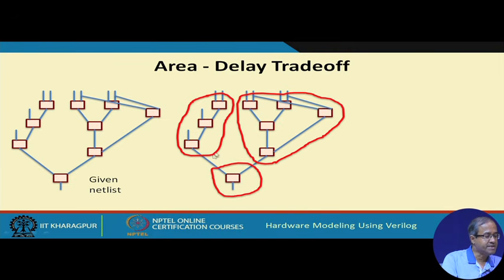If I take this whole part, there are total 4 inputs, 1, 2, 3 and 4. So, overall this is a 4 input and 1 output circuit. Similarly, this whole thing is 1, 2, 3, 4 and 1 output. So, any sub circuit with any number of gates with maximum up to 4 inputs and 1 output can be mapped to LUT.